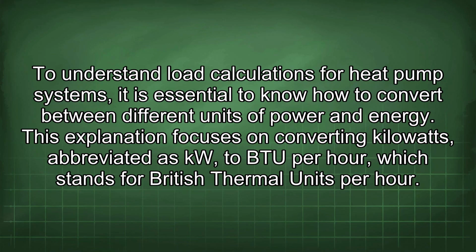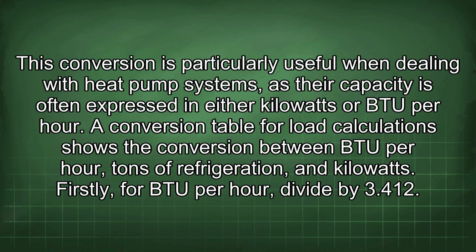To understand load calculations for heat pump systems, it is essential to know how to convert between different units of power and energy. This explanation focuses on converting kilowatts, abbreviated as kW, to BTU per hour, which stands for British Thermal Units per Hour. This conversion is particularly useful when dealing with heat pump systems, as their capacity is often expressed in either kilowatts or BTU per hour.